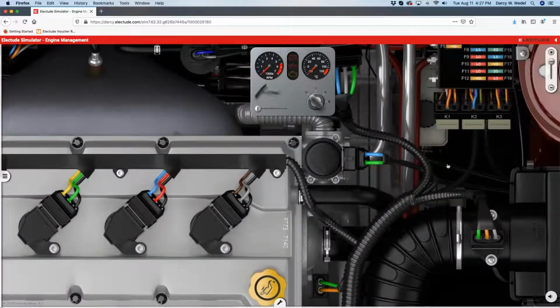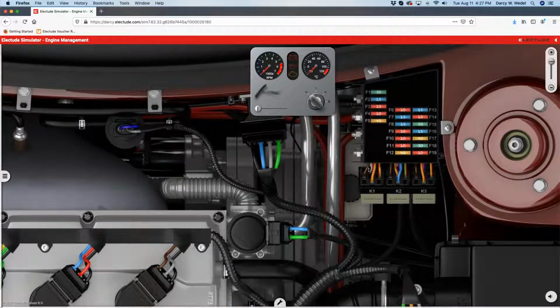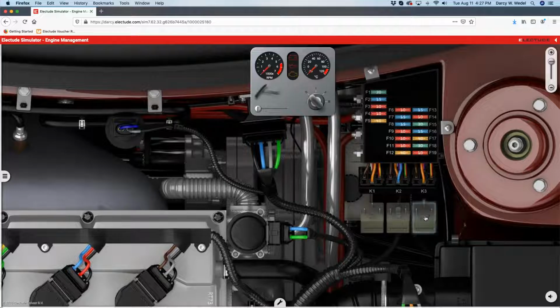In regard to the relays and things like that, you have your wire colors that you can look at here as well, and then you have your relay views, and you can compare that with the scan tool for your pinouts and things like that. So by looking at the orientation of the pins together with the colors, most students should be able to identify these pins fairly easily.